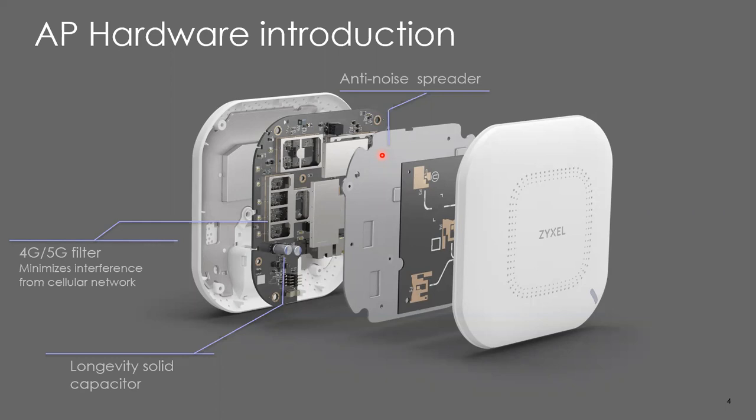You will also notice a lot more RF shielding on the PCBA itself. If you look at our competitors, you'll normally see one or two little sections of RF shielding, where if you look at our PCBAs, you'll see a lot more RF shielding. And again, that's just to help reduce electromagnetic interference on the board just that much and give us just that much better receive sensitivity.